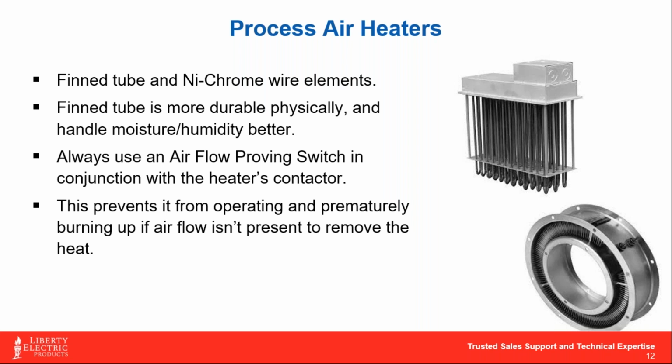An open coil heater looks like the inside of your toaster oven. If you've ever looked down into your toaster oven while it's running, you see those orange hot, almost wire-like elements cutting across there. Open coil elements are basically nichrome cables, or wires for lack of a better term, that are usually connected with ceramic discs because the ceramic can take the heat. They're usually less expensive to produce, and they are very effective. They actually last a very long time as well, but they don't do well in high humidity or moisture applications, where you get some arcing going on inside if it takes in a little bit too much humid air.